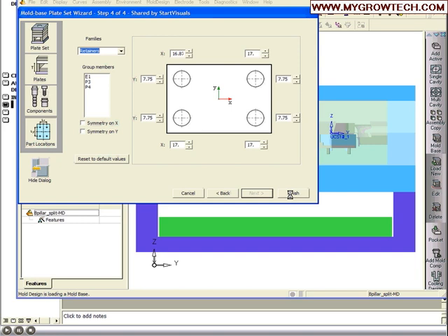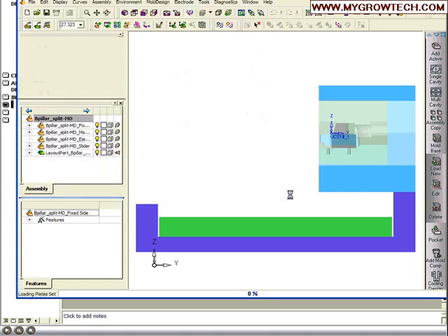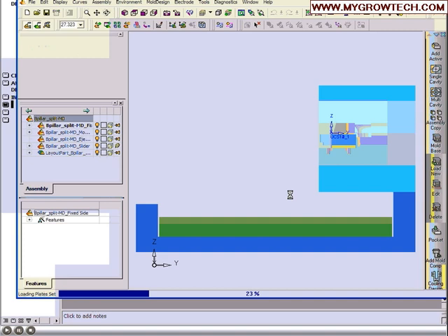You note down here on the button, which takes you right back to these panels so that you can make changes after you've built up the tool. With that done, let's hit the Finish button, and now we're going to build up all these different mold components and assign them into the different sub-assemblies. So as we go through this, you'll see the A side, B side flashing as it's loading those components.